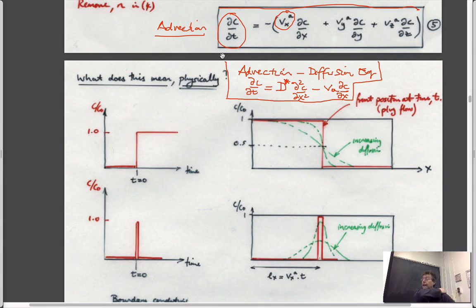So this really is now representing the flow in our little tube, our cylinder of soil. And if we think of it in that way, we can think of this in terms of just three components. This is an accumulation term. This is a term that represents diffusion, spreading, if you like, by diffusion. And this is a term that represents lateral, longitudinal extension by advection.